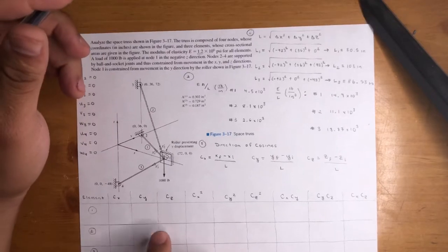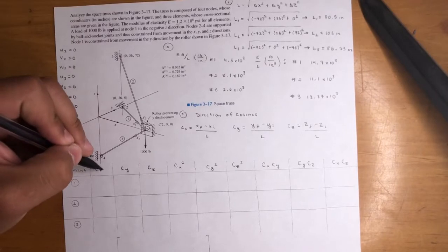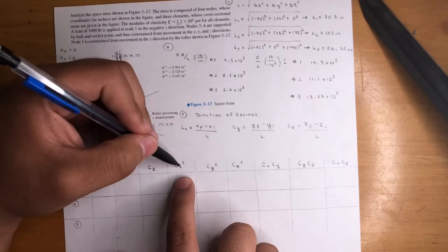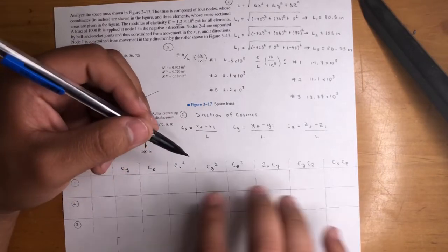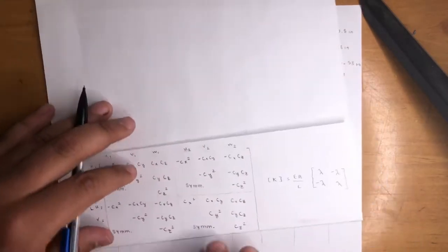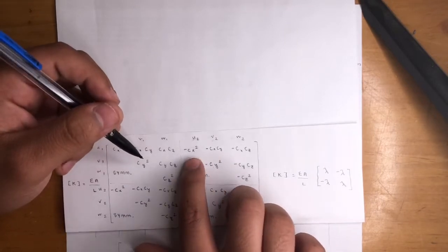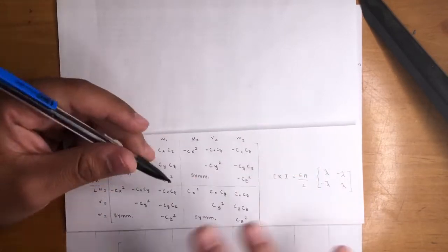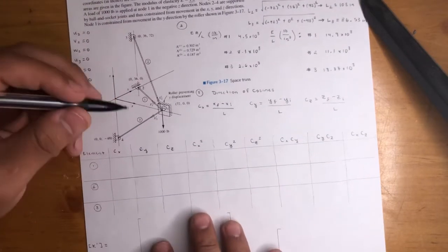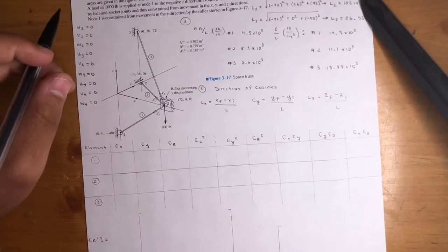So let's go ahead and start filling in this table. The reason I make this table is that you're going to need CX, CY, and CZ, obviously the direction of cosines, to get the squared values. And the reason these values come up is because from your matrix, we have to fill in this matrix for each element. It needs CX, CY, CX squared, CY squared, CZ squared, and the rest are just a combination of all of them. That's why we need to do this. You're also going to need these 3 when you're finding stresses. But when we get there, I'll explain that.